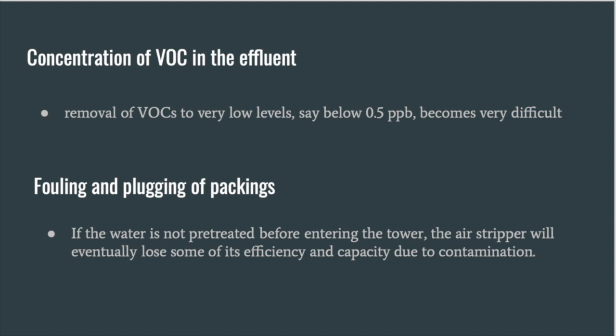In air stripping systems, paradoxically, the high mass transfer efficiency of the stripper promotes the deposition of insoluble metal oxides and the growth of bacteria. High surface area will be more effective, but will also promote fouling.